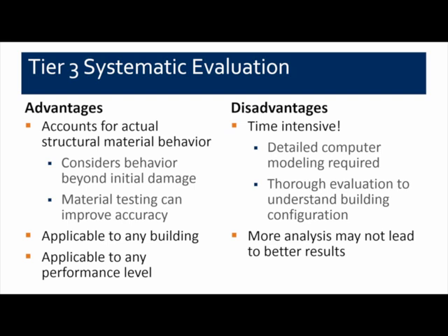The main disadvantage to doing this systematic evaluation is that it's very, very time intensive. It requires lots of detailed computer modeling, and a thorough understanding of all the building components, their configurations, and their structural properties. And doing this systematic evaluation doesn't necessarily mean that you're going to get any better results. You're not going to necessarily get better results using a more sophisticated analysis. In some cases you will, but in other cases more analysis may not do you much good.